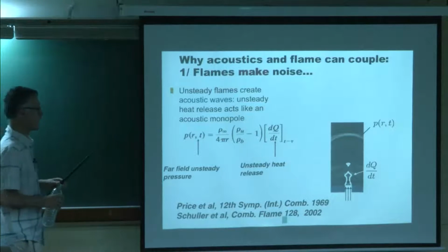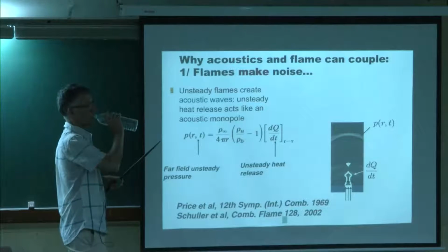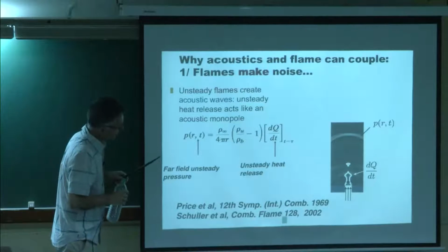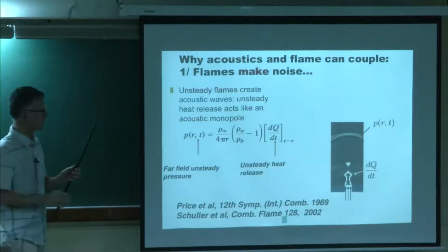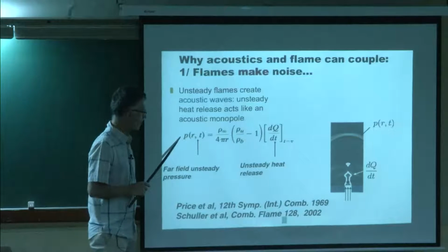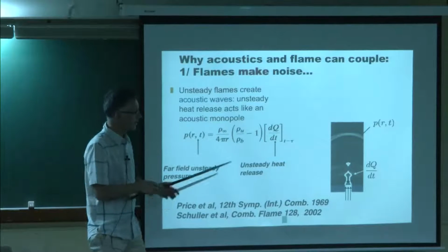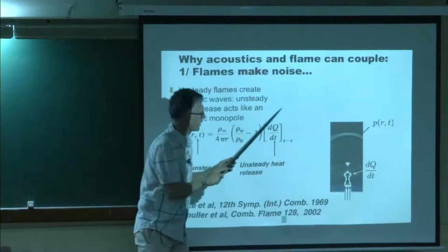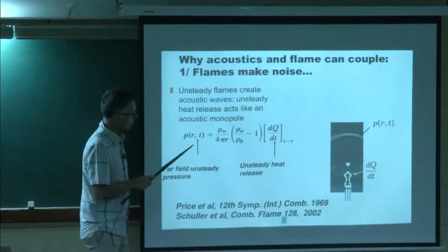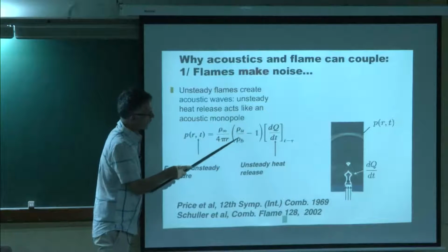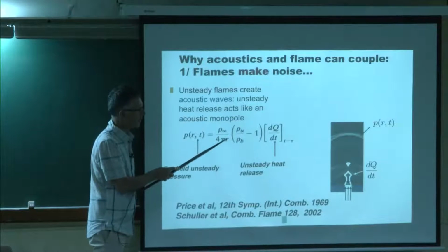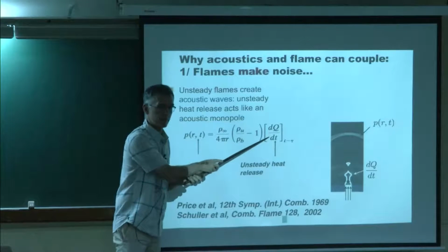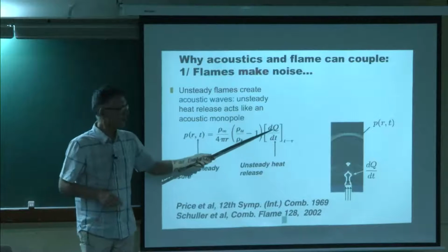If you take a free flame, you can show, it's actually a good thing to do, it's quite easy. If you write the momentum equation and integrate it from here to infinity, you can show that the acoustic pressure is a function of the density ratio multiplied by some scaling parameter, decaying like 1/r, and here you have dq/dt. dq/dt is the unsteady reaction rate.